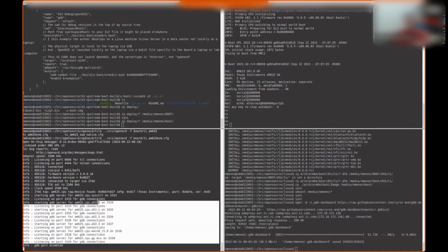This log is very important, and you can control which network port it can open to. I have given support for almost all the standard processors. The ones that I have not supported at this point are C7x and C6x. Unfortunately, that information is not public domain, so I cannot, quote unquote, open source it. So if you're working on the C7 or C6 DSP solutions that TI has, you will have to work with the higher-end debug tools. Both CCS and Lauterbach do have support for that, so you'll probably have to switch over to that.